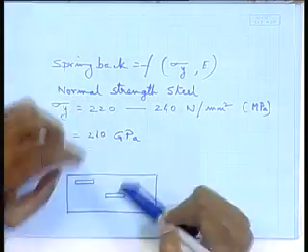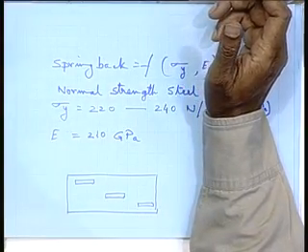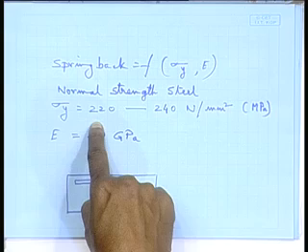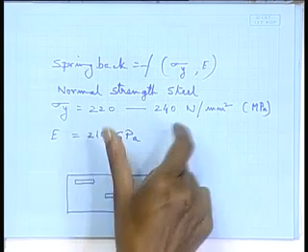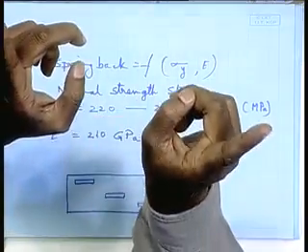That means the material property, this steel material, is not a so-called material of unique property. I mean, it is not made of a single crystal where anywhere only one single physical property will be there. No, steels are qualified to a category of steel depending on whether it is falling within that prescribed zone. This is the prescribed zone for normal strength steel, right? But the zone is wide enough to get my springback value also wide enough. So that becomes the problem.